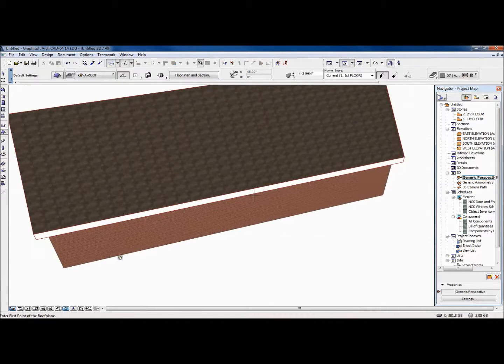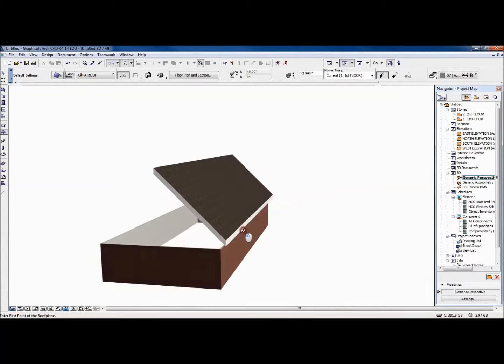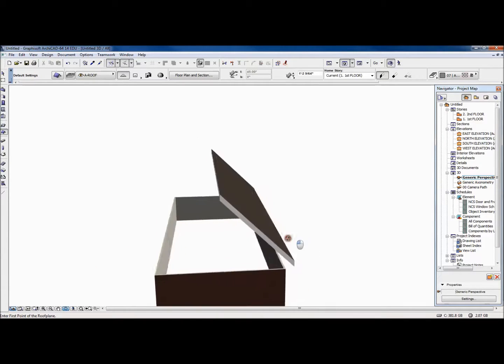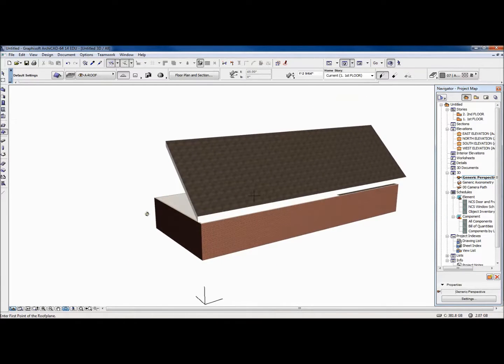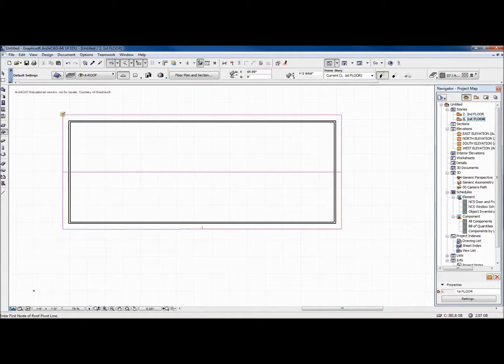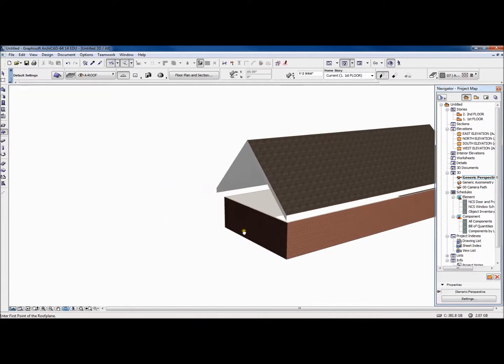I will look at that in 3D now, and I will rotate this, and you can see then what we have done. We've put a 10-12 pitch, and we have hinged it on this side of the wall and put the ridge up on this side. And so I'm going to go back to the F2 function, and we'll do this side of the roof plane. This is the hinge. We want it to look toward the ridge, and now we must trace the actual roof panel. And so now it should be done. I'll tap F3. Okay, so there is that section of it.